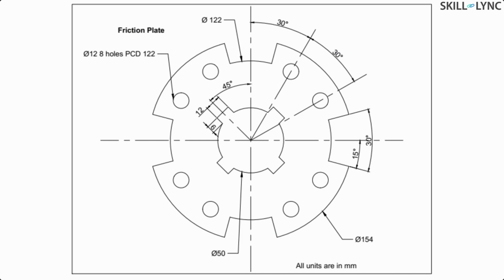So now let's practice the friction plate drawing that is shown here. We'll try to use all the tool commands that we have seen so far. In today's session we have seen different navigation techniques, selection techniques, and zoom commands and all. So let us try and use those. And parallelly, last week what we had seen was using different editing commands such as move, copy, array, break, mirror commands. And previous to that, we were seeing circle commands, arc, rectangular commands, and line commands. So we'll use these fundamental base commands to draw this diagram.